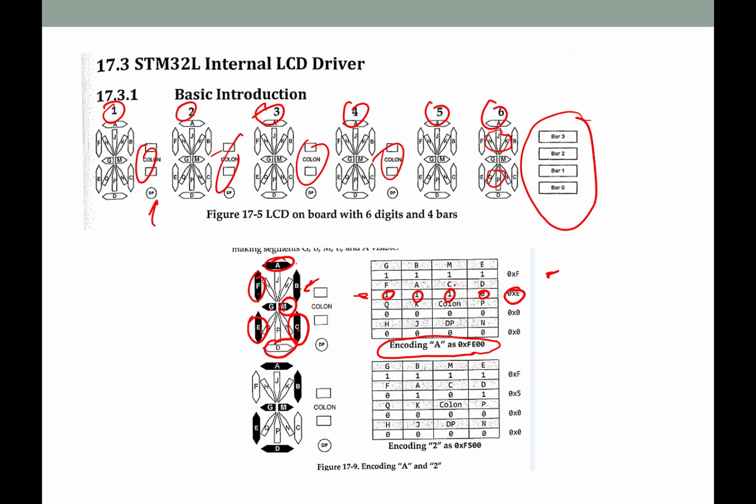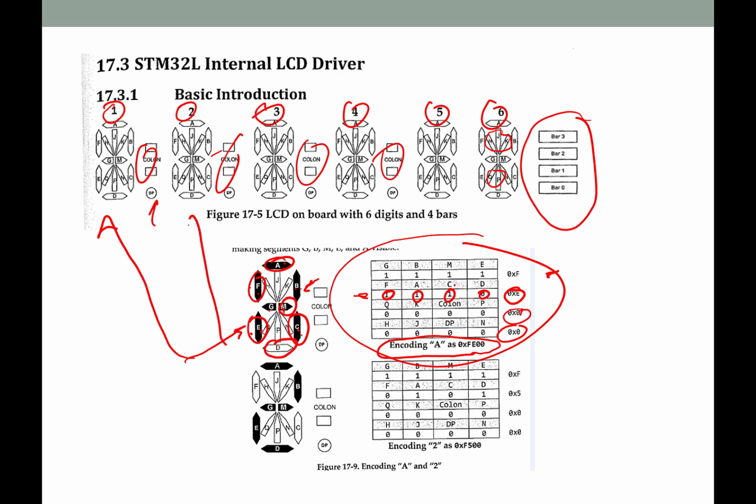Well, since we've basically gotten all of the others, we know we needed to light 1, 2, 3, 4, 5, 6, 7 segments. All the other segments don't need to be lit, so that's why these are zeros. I could go through them in painstaking detail like I did these, but that's how we would encode that. So this has to get there for the specific digit. Was it that digit? Was it that digit? And so forth. Because we've got 6 digits we could light.